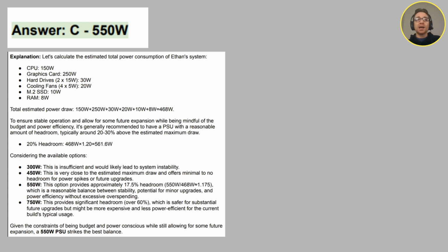So basically, guys, if you add up all those wattage components, that is the one that meets the power requirement, but also allows for some headroom. They did say they want to allow for some headroom. All right. So that was key there. They want to allow for some headroom. 468 watts. If we go straight with that, we're not really going to be able to add a lot more on. But if we go with a reasonable 550 watts, then absolutely there's some headroom there.